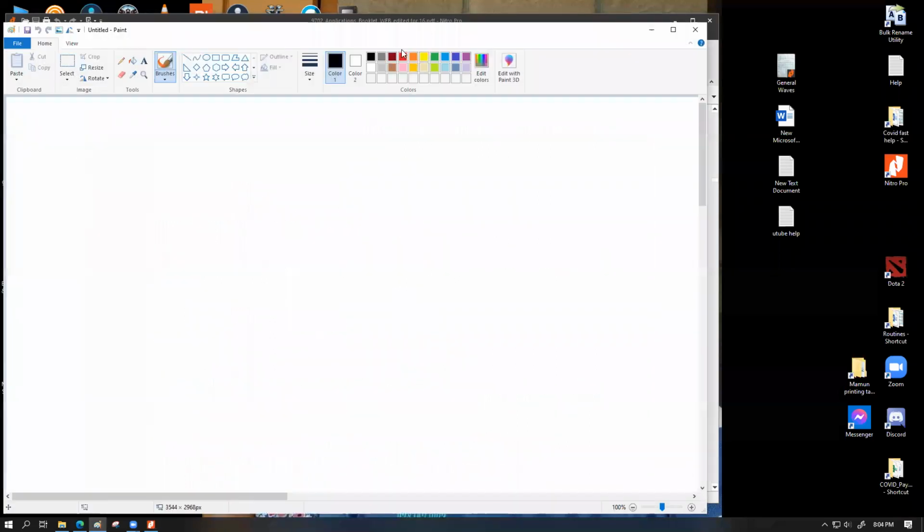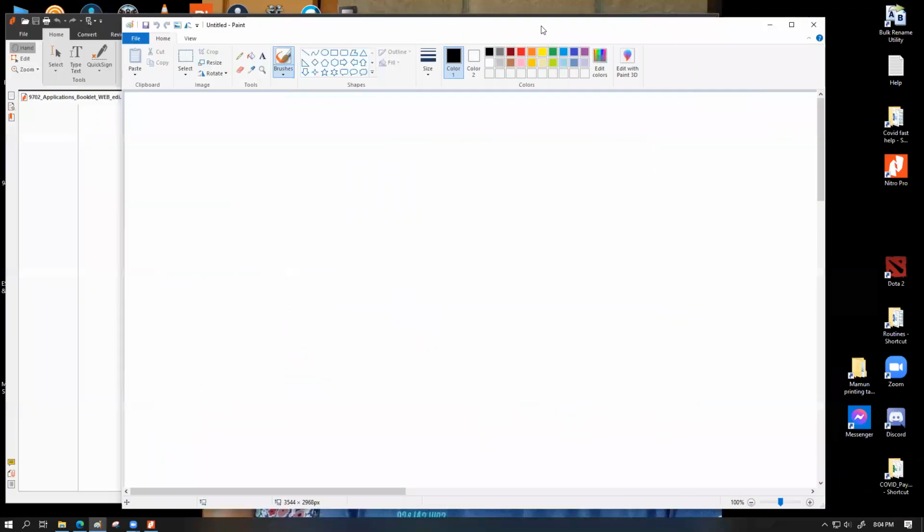What I mean is something like this. Let's say in this scenario our V plus was 1.4 volt and V minus was 1.3 volt, and the V out was calculated to be 10,000 volt. Now, if by some happening this V plus increases from 1.4 to, let's say, 1.41 volt, so there is a change of the V plus value, one of the inputs is undergoing some sort of change.